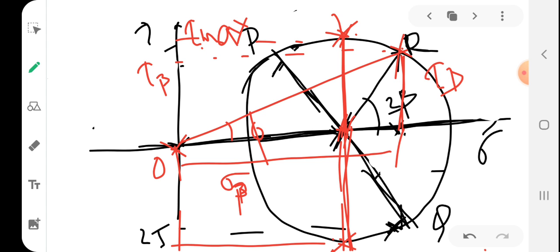The plane which gives you the maximum possible shear stress is actually 90 degrees from the principal plane. So the angle between the plane which gives you maximum possible normal stress and the plane which gives you maximum possible shear stress is 90 degrees apart. Things will be more clear to you when you do some problems, and in the next session we can do problems.